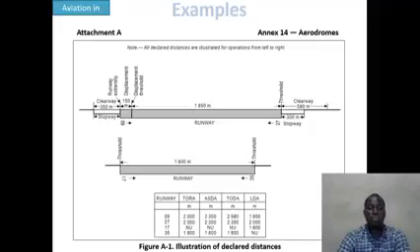On the runway 09, the TORA is 2,000 meters, the ASDA 2,300 meters, the TODA 2,508 meters, and the LDA 1,850 meters. So, for example, the displacement here is 150 meters, so the LDA will be the TORA minus 150 meters.